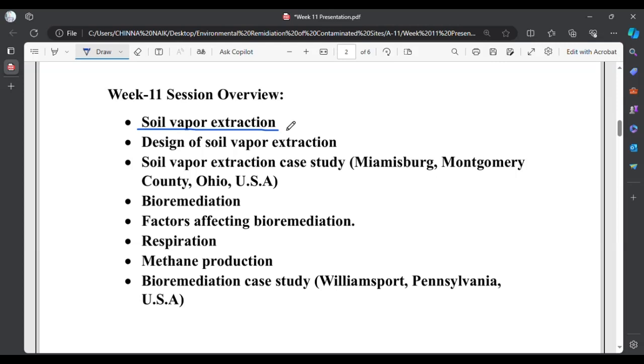What we are doing here is simply not adding any reagents or chemicals. We are just introducing air, I mean gas, to the contaminated soil media or liquid media, and then whatever the NAPL, DNAPL, LNAPL, mostly hydrophobic contaminants, will change phase from solid to liquid, and to a gaseous phase.